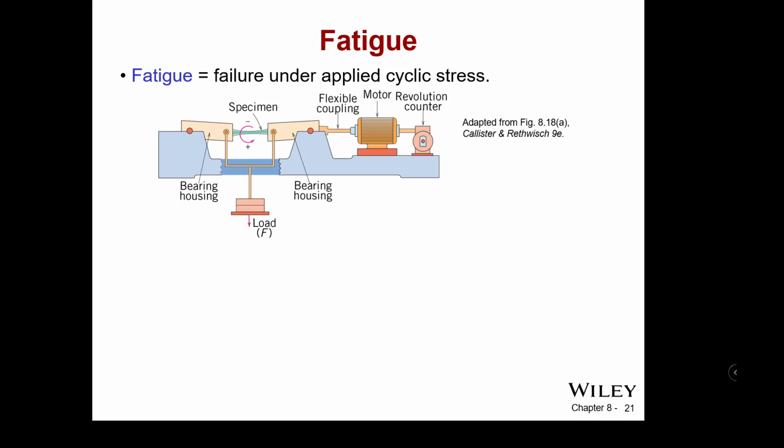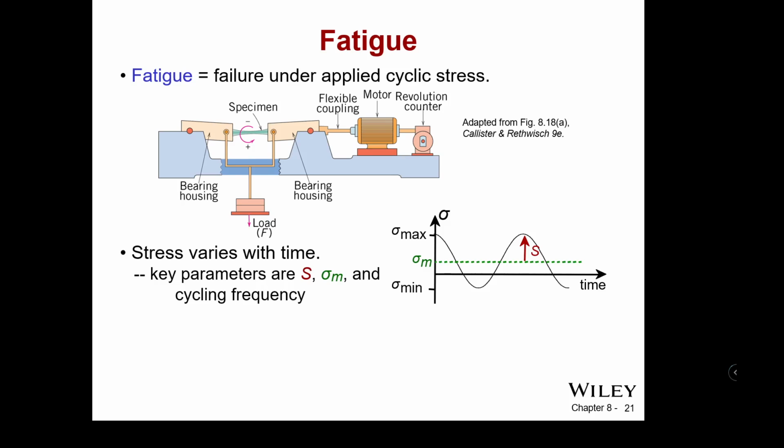You develop load cells using strain gauges, and that allows you to connect a specimen between these bearing housings in order to test them. You have some sort of coupling and a motor actuator and some sort of counter to keep track. The stresses vary with time.